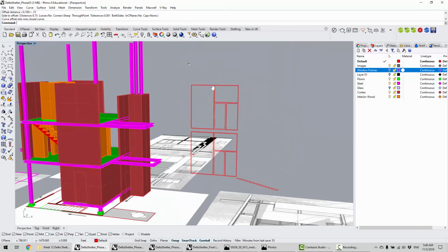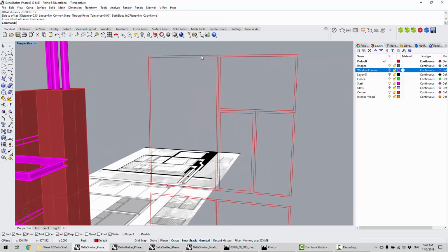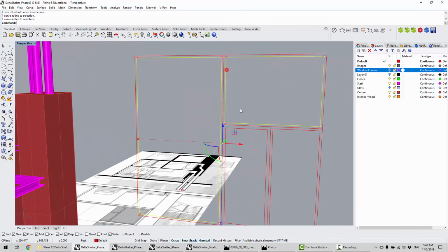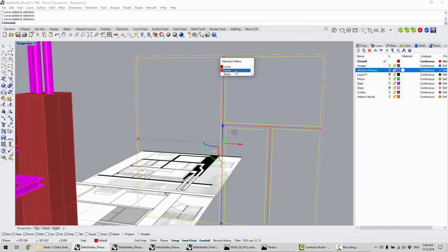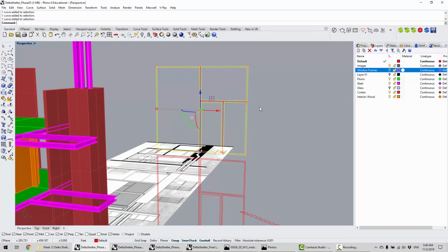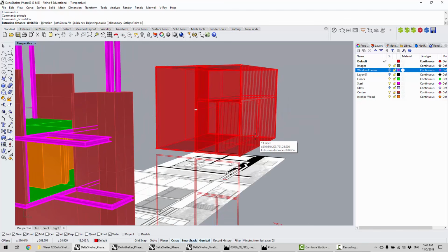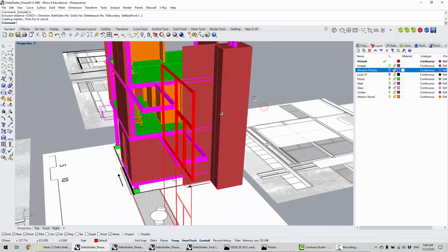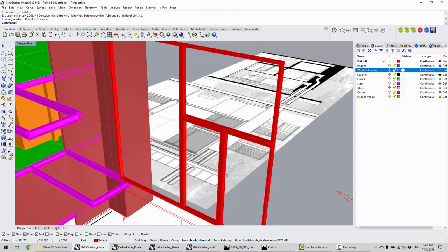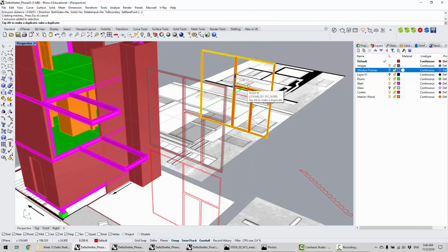Then what I do is select all the inner curves, and the big outer one, right? These are the ones that, when you extrude and give it a thickness like 0.2, for example, should give you one large frame like this.